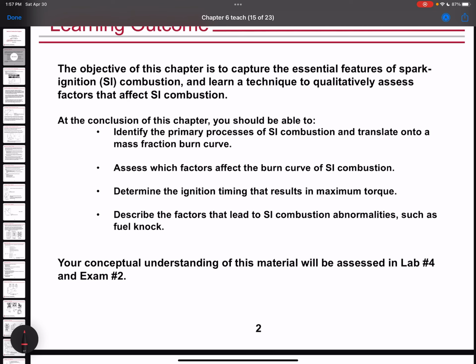In other words, we would allow combustion to occur either as constant volume, constant pressure, or a combination of the two, what we, of course, call the limited pressure analysis. And none of these three are realities of what actually takes place in an engine.